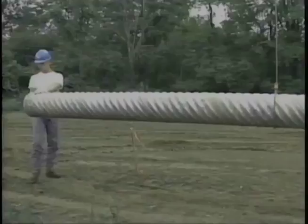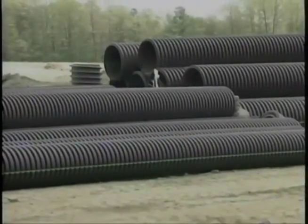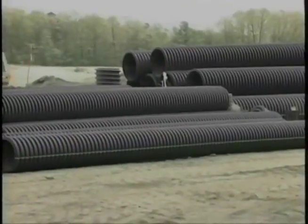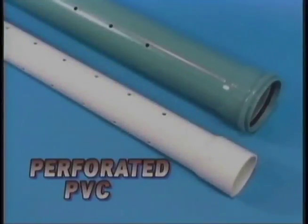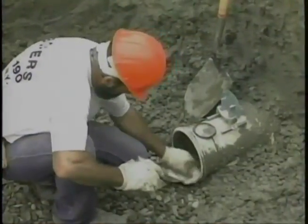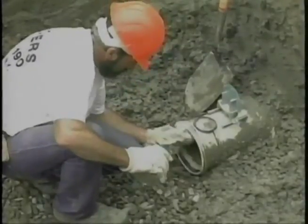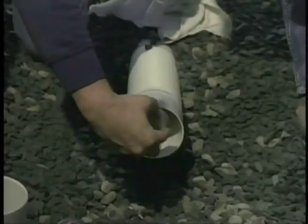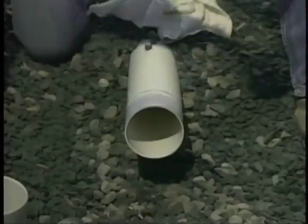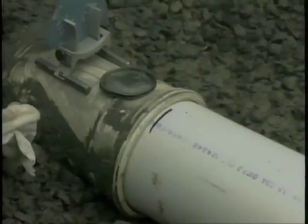Polyvinyl chloride, corrugated metal, and corrugated polyethylene are common types of pipe used for subdrain systems. PVC is often used in drain field applications. Standard joint lengths range from 12 to 20 feet. Two types of joints are available. Slip-on or push-on joints require grease for the installation. Solvent cement joints require a primer and glue. Install these joints using the same steps as bell and spigot pipe.